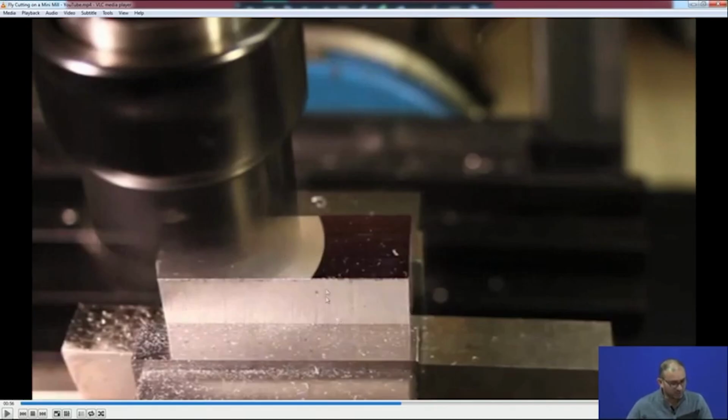So, you have to remove those tool marks at the later stage, but here we are actually using the circular motion. That means, whatever is the radius of this particular cutter, the same radius of concave surface you can create on any workpiece or optical material without any problem.